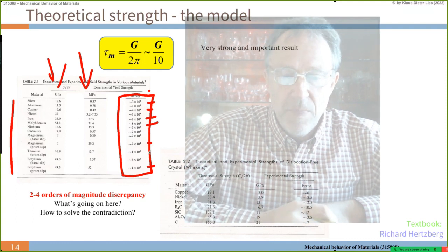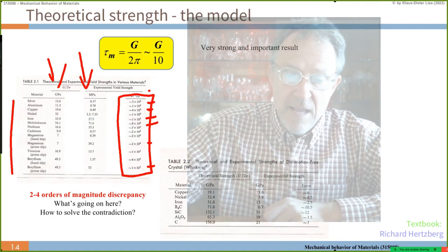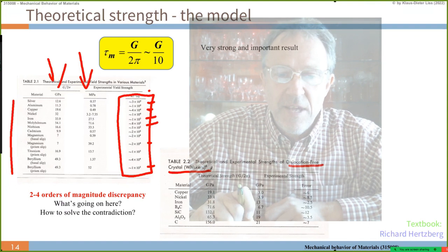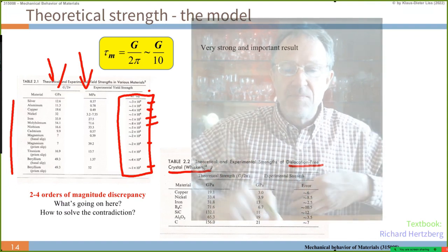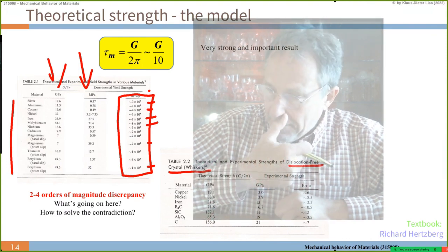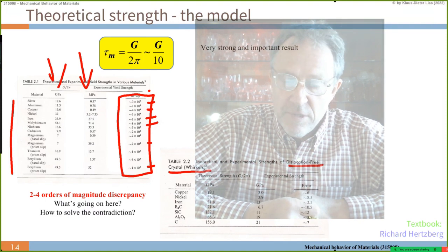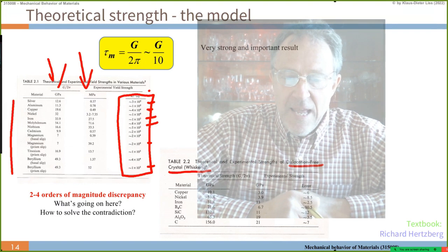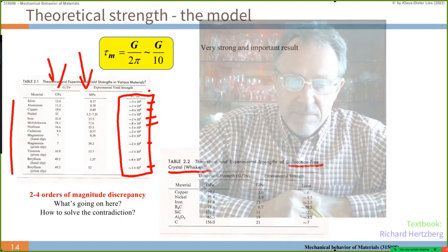So there's a problem. Then people looked at the theoretical yield strengths of a dislocation-free whisker. This is a crystal without any dislocation. A whisker is a very tiny, long crystal, like a string, with a certain zone axis, and it is crystallographically perfect. Sometimes it has one dislocation, but this is basically a dislocation-free crystal, and they are about the strongest materials you can find.